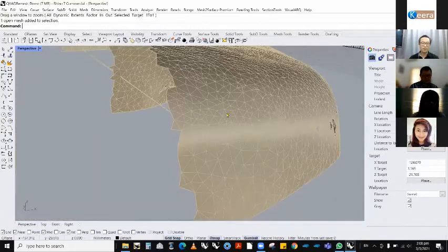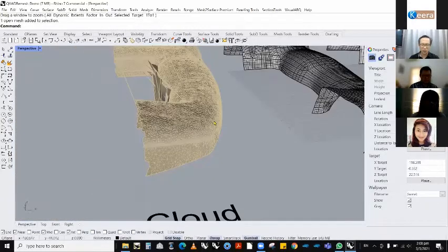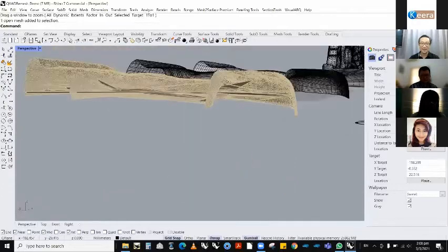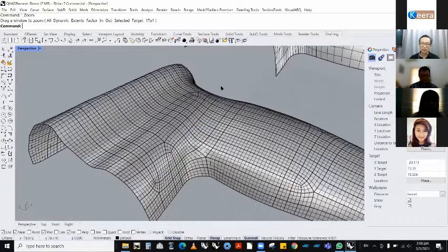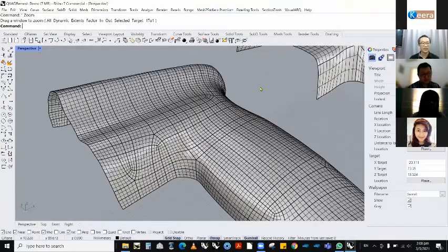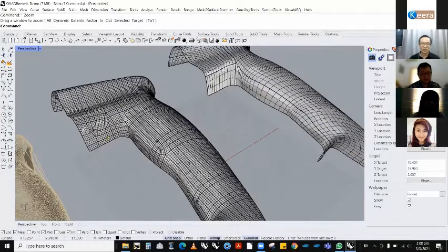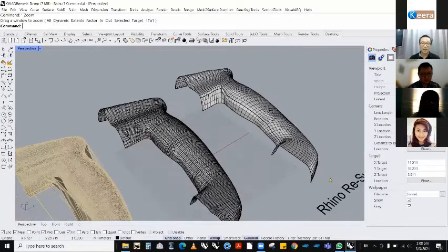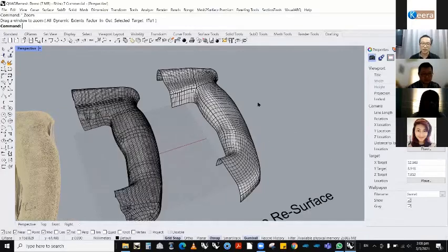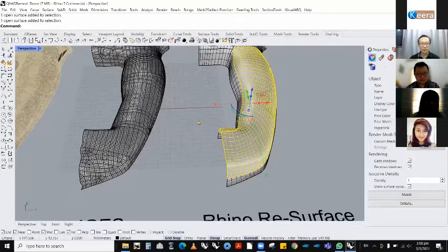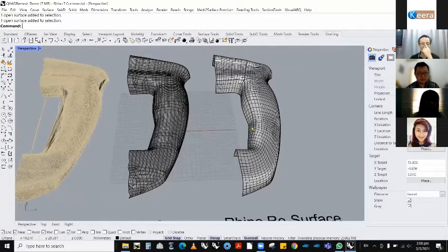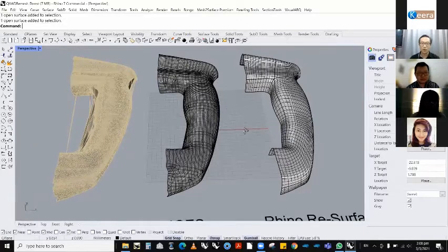Okay, the point information, and then it's a mesh, obviously it's a mess. So we used Rhino to slowly articulate this, and then we used Mesh to Surface, a reverse engineering software, to help us tabulate some of the information, and eventually we used Rhino to resurface the whole thing. If we want to move this to NURBS, we can. Skipping this part here. This was a bit painstaking, but we were okay with it at that time when we were working with the scanner.